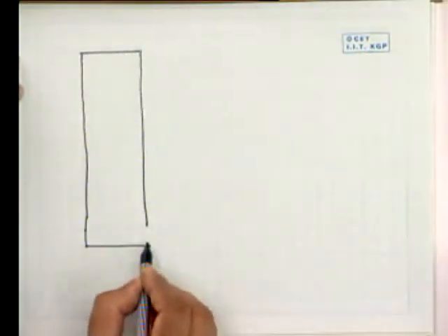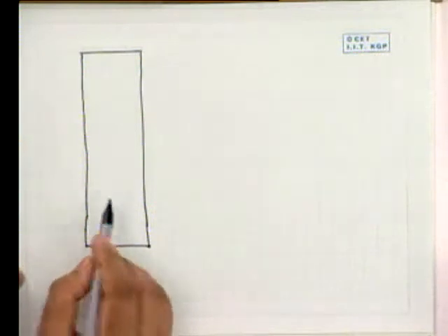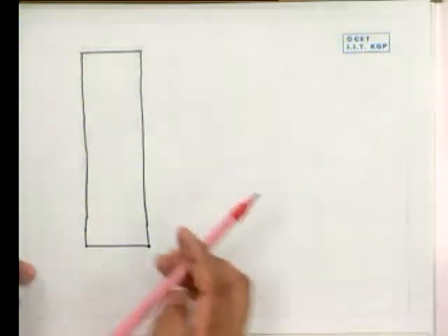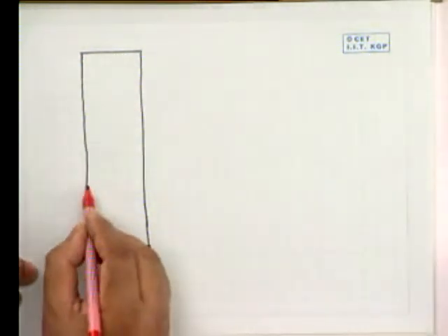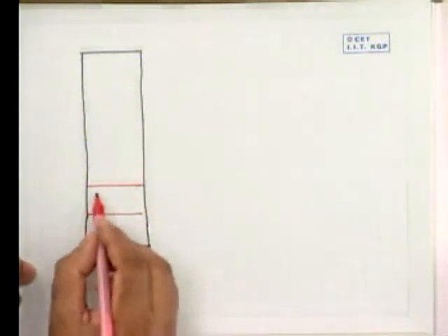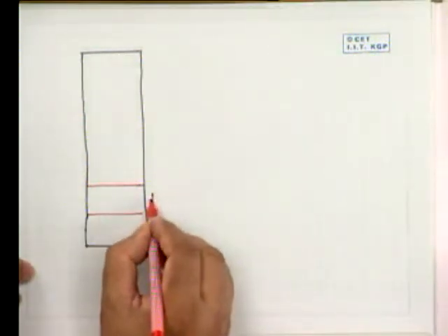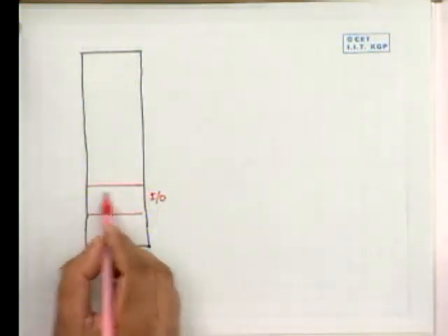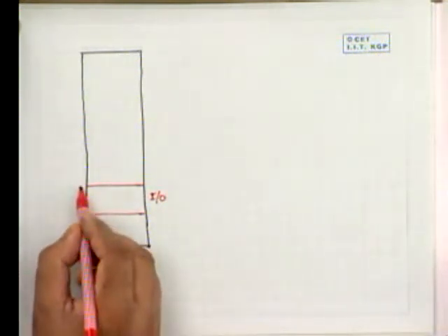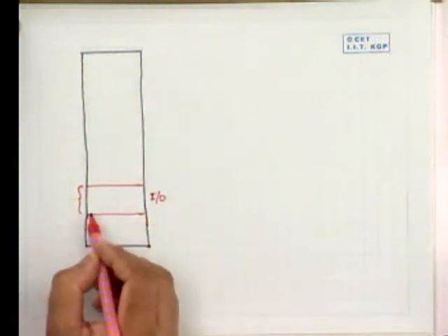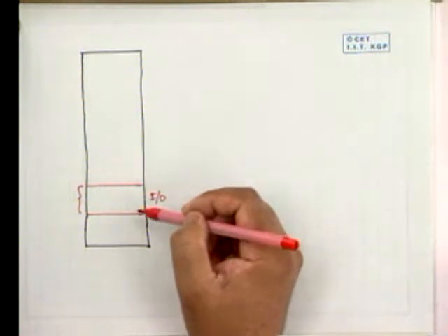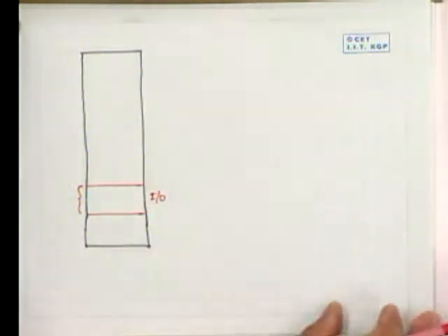Say this is the addressable portion that the CPU can address. In this case, when we are talking about memory mapped I/O, some portions of the memory, say these portions, we choose and map to I/O. That is called memory mapped I/O. Here all the device registers, by that I mean the interface registers, are mapped. That means from this to this, a portion of the addressable memory space is dedicated for I/O purposes, and such a situation we call memory mapped I/O.